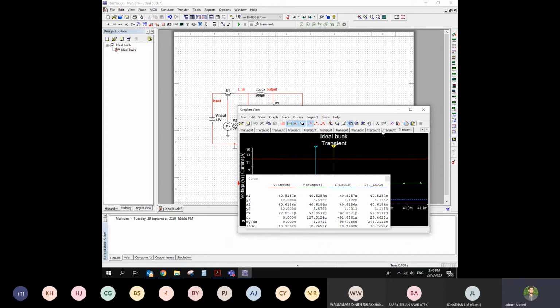But you can see something. There is a certain threshold for the output voltage to get reduced. It will not go below 5.4 or 5.57, even if you choose very different values, as long as you run it at some operating condition. The deviation of the output voltage will not be very high from the ideal value. It will be somewhere between 5.5 to 6 or 6.2, 6.3, something like that. But if you change the operation on a very large scale, then the value is going to get really affected. But what will never happen is, this is a buck converter. So on the output side, you will never be able to get more than 12 volt. It will always be reduced voltage on the output side.